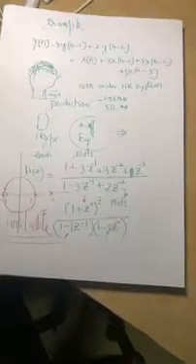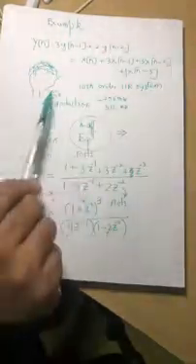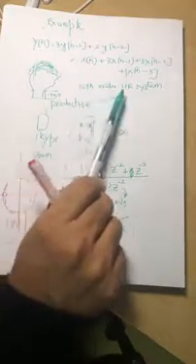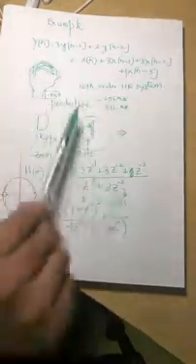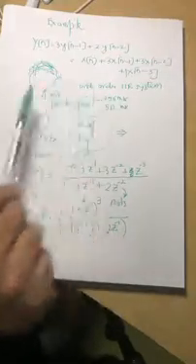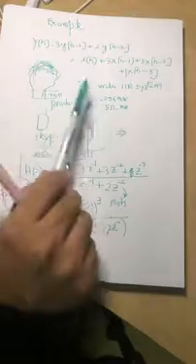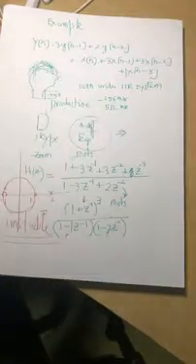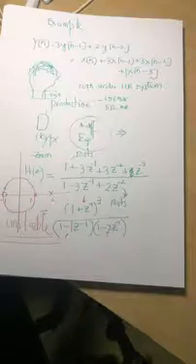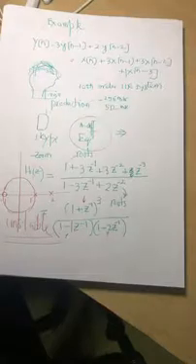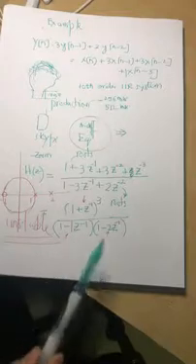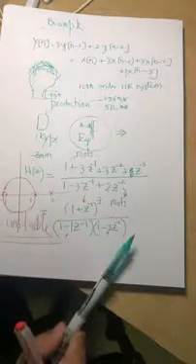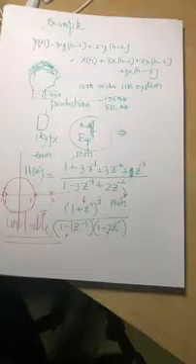So whenever we are given a difference equation, finding out the roots, and remember for speech you need to find out a 10th order polynomial. This is a 10th order polynomial. So there are very interesting techniques people have devised, because you have to do this in real time. Factorizing a 10th order polynomial is quite a task, but thanks to people like Levinson and Durbin, who have come up with the recursion that helps you find all the poles of the system. So this is an unstable system. Okay, so this is how we check the stability.